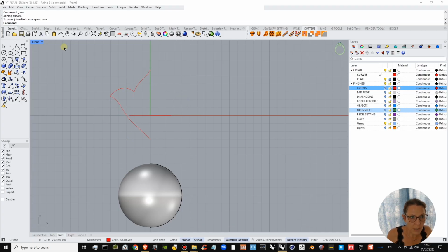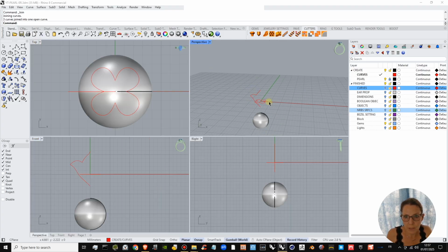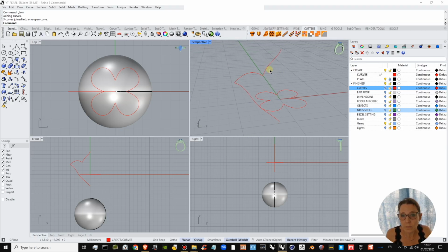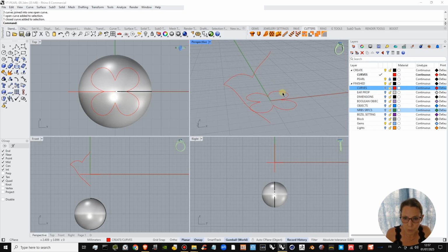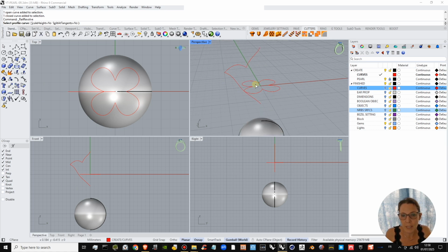Well, because this curve is going to become a profile curve for a rail revolve. This curve isn't quite finished yet. In fact, these points are maybe too far in, but we'll see that in a moment. I first just want to do the rail revolve so you can see what kind of result you get with curves like this. And I'm just going to create one more layer.